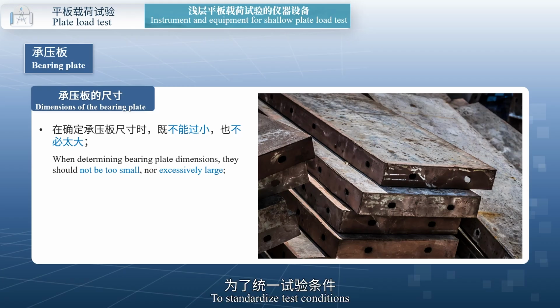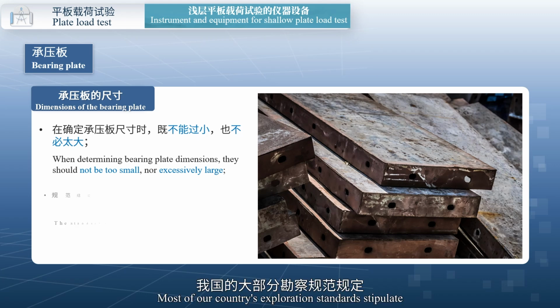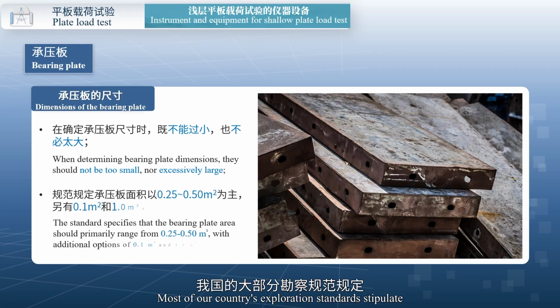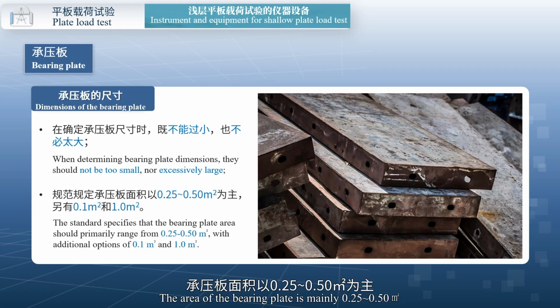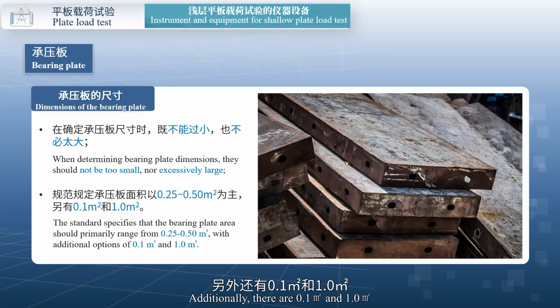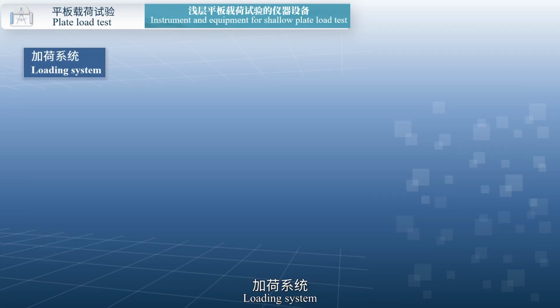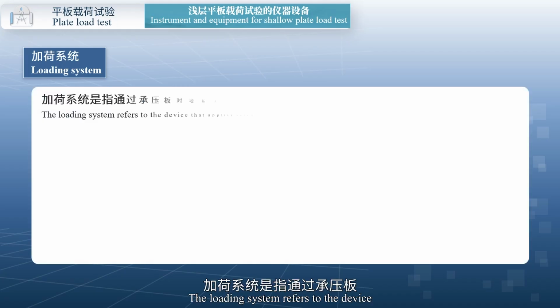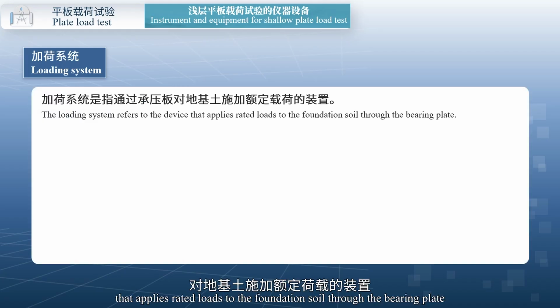To standardize test conditions and make the test results comparable, most of our country's exploration standards stipulate that the area of the bearing plate is mainly 0.25 to 0.5 square meters. Additionally, there are 0.1 and 1.0. 2. Loading system. The loading system refers to the device that applies rated loads to the foundation soil through the